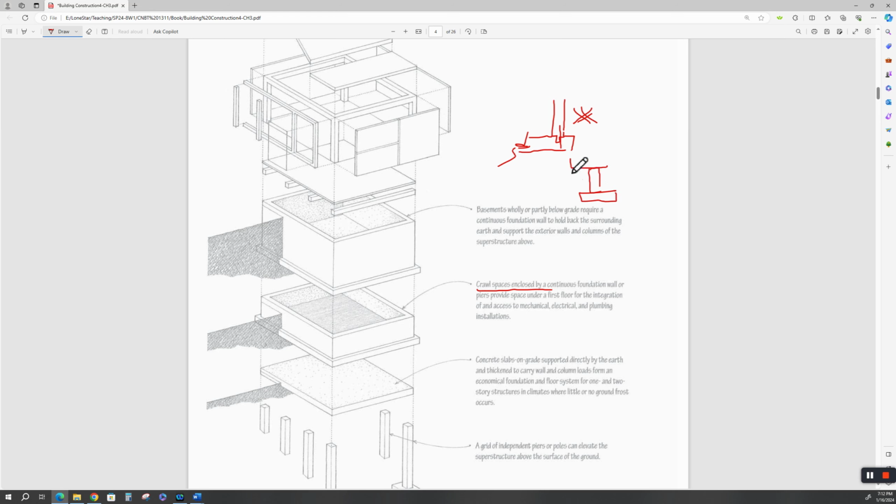There's the floor joist, and then the house is built up on those. And then you have an enclosure for the crawl space, usually on a small footing, and it's a small area underneath the house. A lot of houses in the ancient days of yore were built like that. Our houses now are slab on grade, especially down here. Concrete slabs on grade, which is what we have in this area.